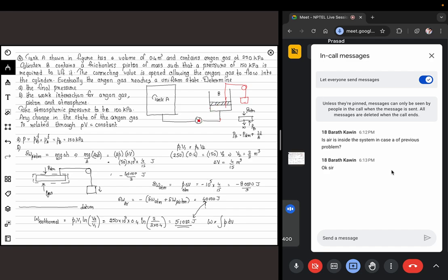So now, in order to have a slow process for which all these equations have to be valid, you need a slow process. To ensure a slow process, you need to open it slowly, like you open the cap very slowly, so that this rushing won't happen. So in order to open it slowly, you need to continuously spend some energy, and that energy is what this difference is accounting for.